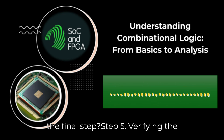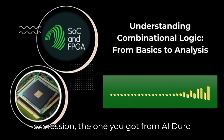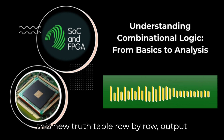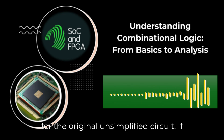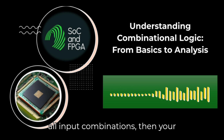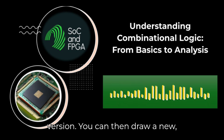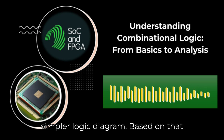Step 5. Verifying the output. Crucial. You take your simplified expression, the one you got from algebra or the K-map, and you create a brand new truth table just for it. Then you compare this new truth table, row by row, output by output, with the truth table you made for the original unsimplified circuit. If the output columns match perfectly for all input combinations, then your simplification is correct. Exactly. The analysis is complete, you know the function, and you have an optimized version. You can then draw a new, simpler logic diagram based on that simplified expression.